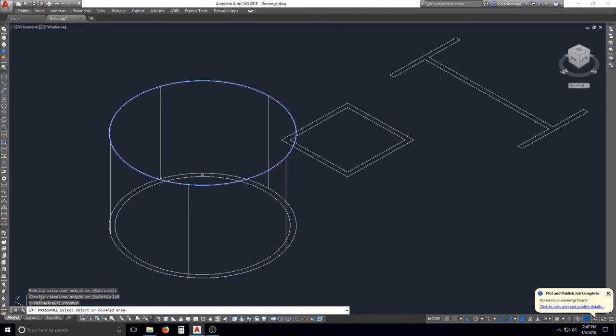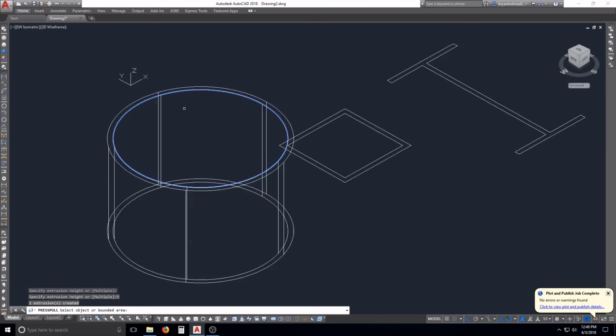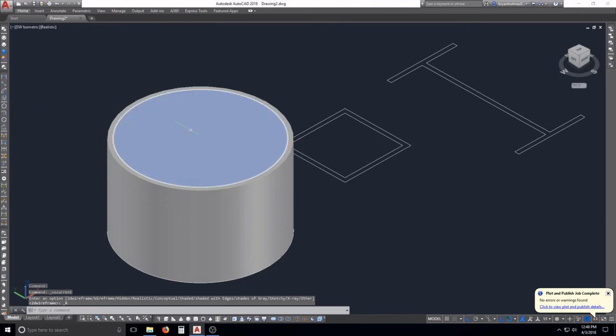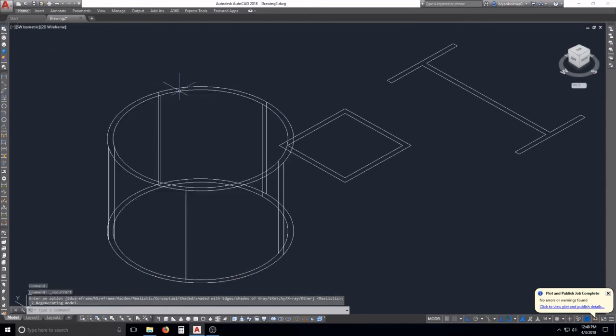And let's do it again for the center one. We're already in the command, so press pull is already selected. And again, we'll type in 5. Bam. So next thing we would do to make this one shape, because if you look here, guys, you can't really tell what we've done. It looks like one solid shape. But if you're in 2D wireframe, it kind of does look like we're complete, but we're really not.